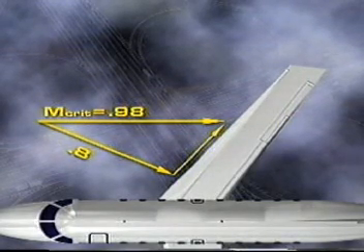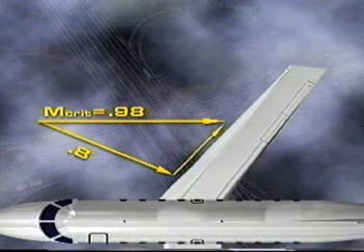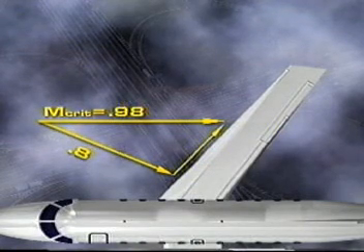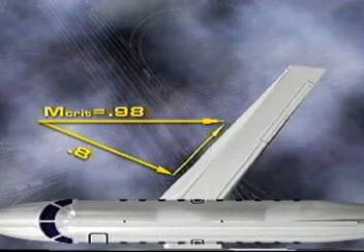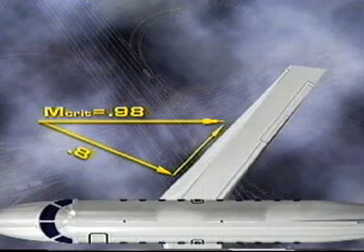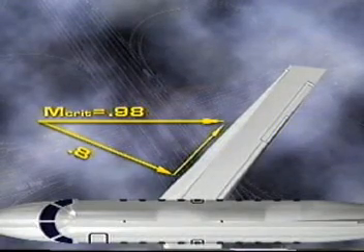This latter component can be seen to have no effect on lift or drag, since the air flows along lines of constant elevation. The pressure distribution is affected only by the flow perpendicular to the leading edge, and it results in a component less than the chordwise vector. It is apparent that the free stream velocity can be increased over one wing without sweep. That is, the critical Mach number of a wing with sweep is increased over one without sweep. This is why a high-speed aircraft has swept wings.